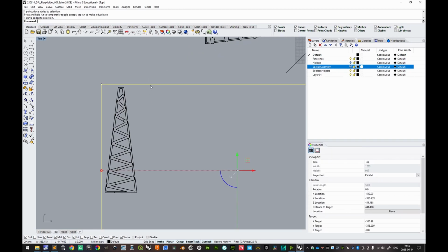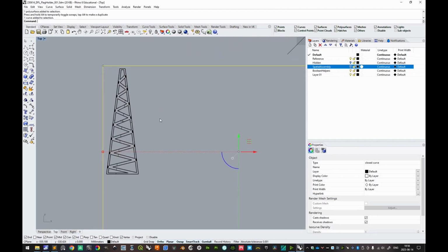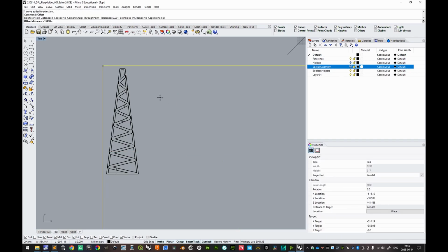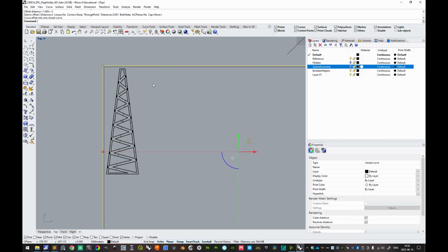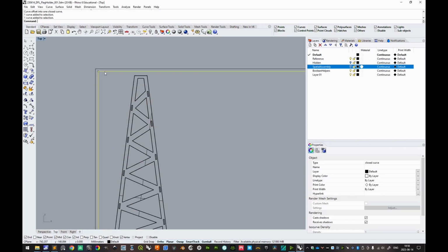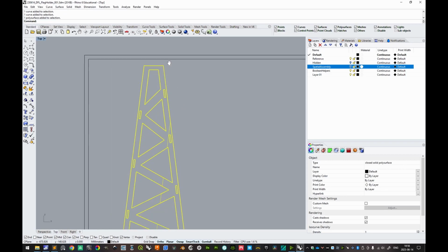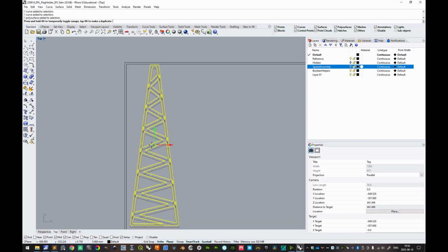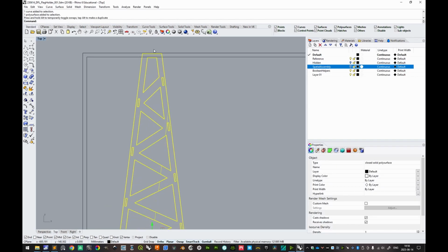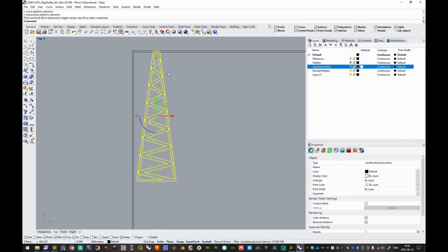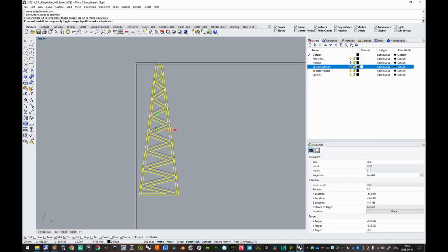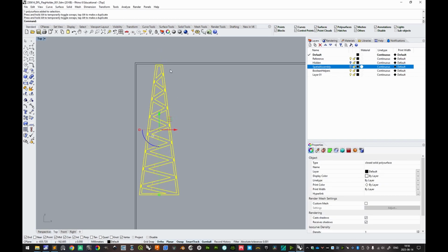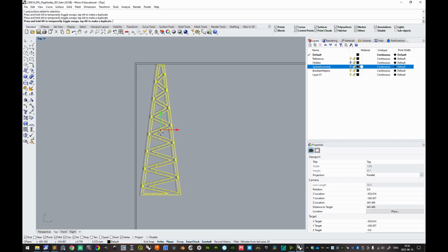It's always good to have a margin. I would recommend 5 millimeters, but at least 3-4 millimeters. So we'll do an offset of this, a distance of 4 millimeters. So we know that this is the maximum work area, and this little margin is there because otherwise the inconsistencies in the edge of the material, as well as in the positioning of the laser cutter, might result in this edge not being adequately cut if you positioned it like this. So I always recommend a 3, 4 or 5 millimeter margin.